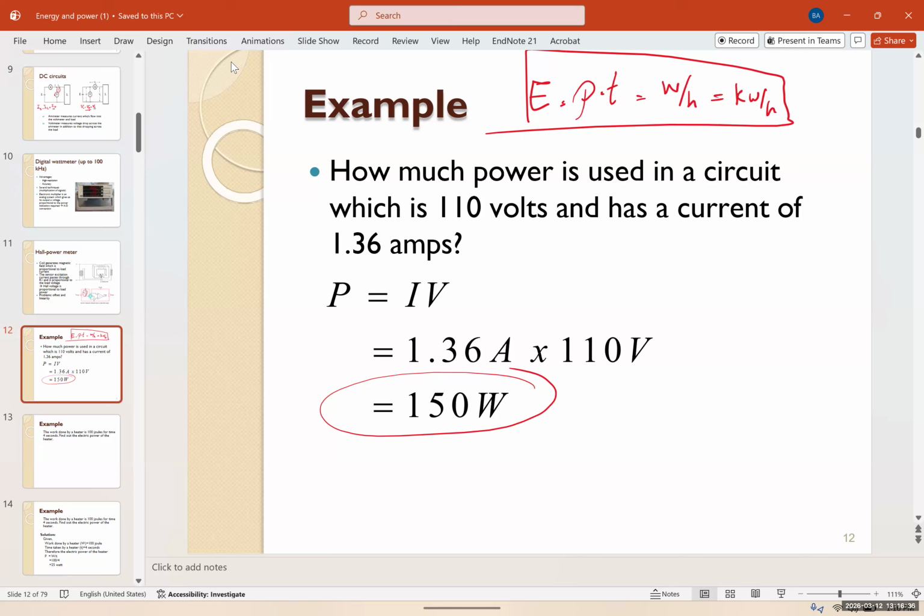So, for example, they would say this wind turbine has generated 10,000 megawatt hours per year, meaning every day it generates maybe 1 kilowatt, but it did it for 365 days. And when you multiply it, this is just a rough estimation. Obviously, wind turbines can't and don't work 24/7, but we measure the total amount of energy produced, not the instantaneous power.